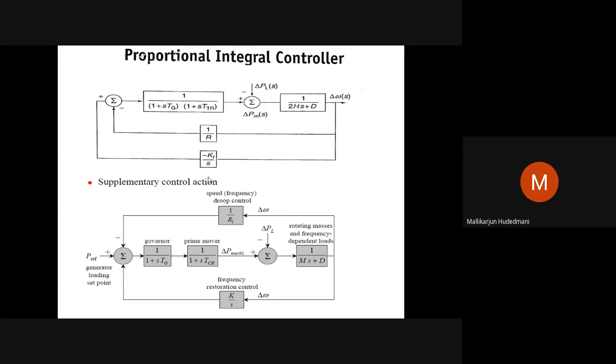These are the two important closed loops of a generator we have seen, the AVR loop and the ALFC loop, in which I am touching the primary loop of the ALFC. That is only to supply mechanical supplement to the turbine. The speed feedback was referred to, so that the speed feedback works and makes the mechanical supplement to the turbine. That was the primary, represented by the first upper half of the representation. That's called speed or frequency droop. By droop, it is feeding back to supplement the mechanical power.